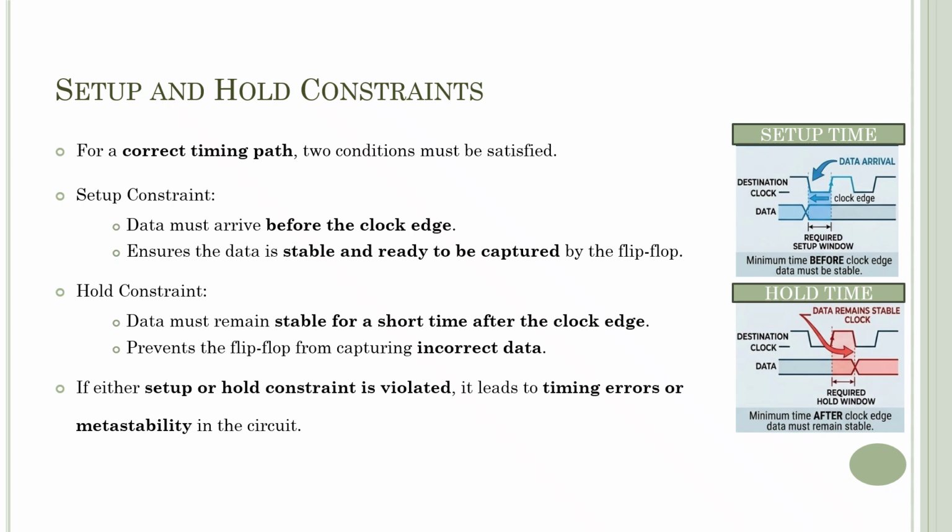In some cases, the flip-flop may even enter a state called meta-stability, where its output becomes unpredictable for a short period of time. This is why, during static timing analysis, tools carefully check all the paths in the design to ensure that both setup and hold constraints are satisfied.